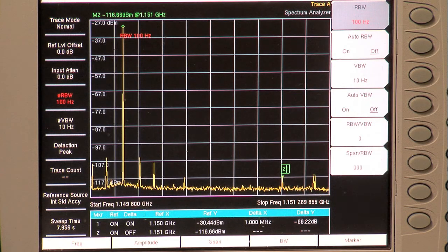Dynamic range is one of the fundamental specifications of a spectrum analyzer, and at the same time one of the least understood. Dynamic range is a measure of the ability of an instrument to measure a tiny signal in the presence of a gigantic signal. There are several ways of correctly specifying dynamic range, and several incorrect ways that are sometimes called dynamic range. The key concept is that dynamic range refers to the ability to simultaneously measure two signals of widely different power levels.